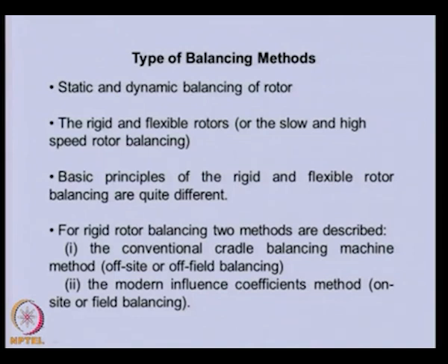Now, once we find that there is a severe level of unbalance, then we need to balance this particular rotor, and there are different balancing methods available, like static and dynamic balancing of rotor.